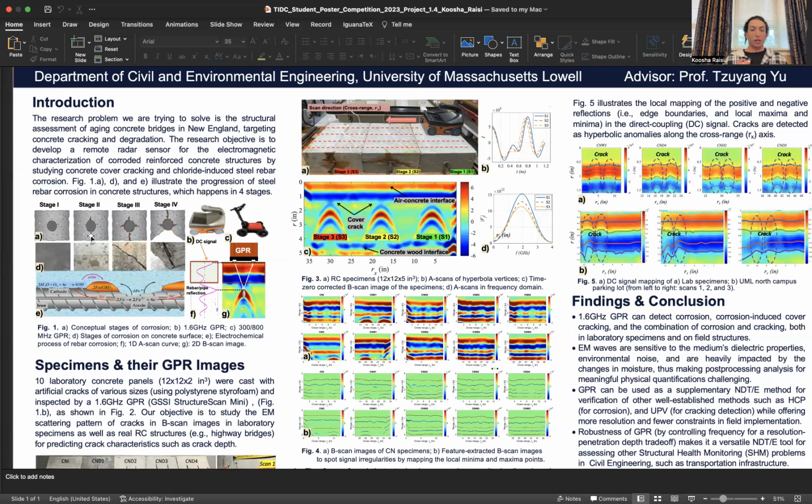And as you know, because of the interfacial transition zone, or the ITZ, the concrete is very weak in terms of tension. Therefore, this stress redistribution causes concrete cracking. It starts around the rebar and gradually comes to the top, where we can see it in stage 3. And quite frankly, stage 3 is where we already can see the crack, so we can attribute it to this. We want to sort of see this before stage 3 happens.